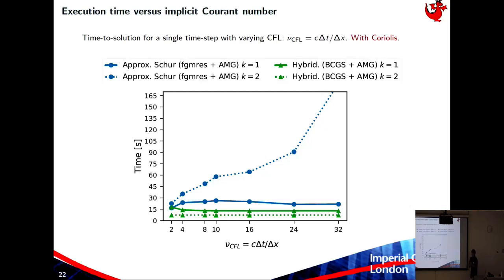So with the Coriolis term, if you're using a diagonal approximation to the velocity term, you're not going to capture the effects of rotation. They appear in the off-diagonal block. So if you're just extracting the diagonal and using that as an approximation to the inverse, you're not going to capture that. And so the operator, that Schur complement, if you think in terms of the continuous space, is approximating an elliptic problem with rotation effects, with a factor of delta t times your Coriolis term.